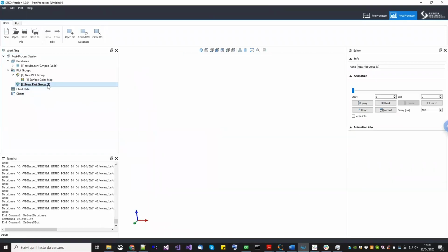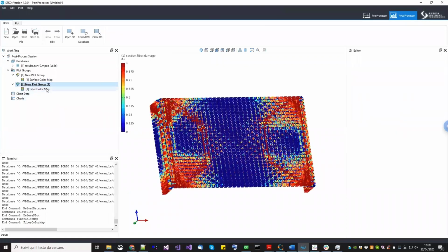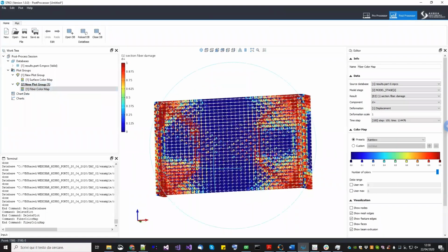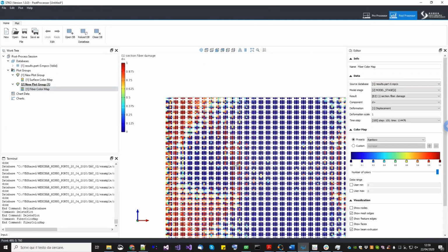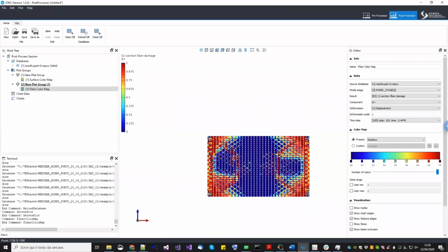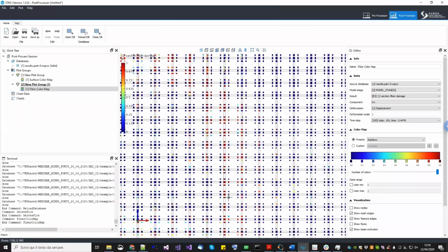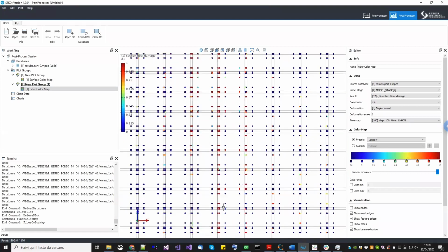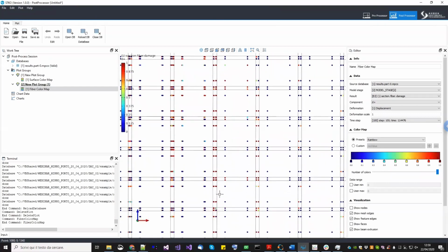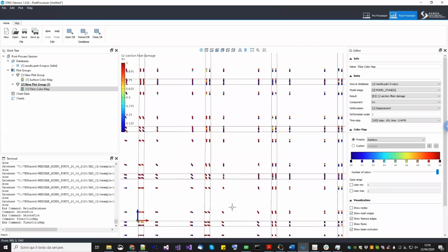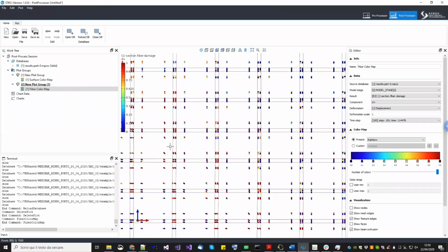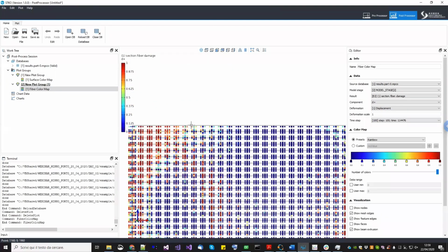And if we look at the damage, in the previous example, there was no damage on the bricks because everything that was damaging was just the mortar joint. Now, in this case, it is not like that, because the mortar joints, since they cannot fail in the out-of-plane direction, become much stronger than they were before. And the crack should find a path also through the bricks. So in this case, as you can see, mortar and bricks are failing, all of them. And then when the crack goes in the diagonal direction, both bricks and mortar fail, like in this case, this is a brick that has failed. Mortar, brick, and basically all of them have failed.